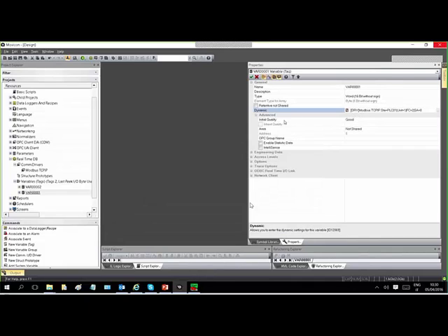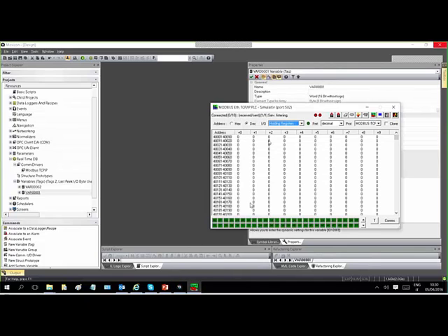It is an example of how the dynamic task is built inside the Movicon variable. It always comes with this syntax: drv, the driver name that you configure, station name, unit ID, function code, and starting address 0. You can copy paste this on a second variable, or edit also in a CSV file. In this way, we create the association with this register.